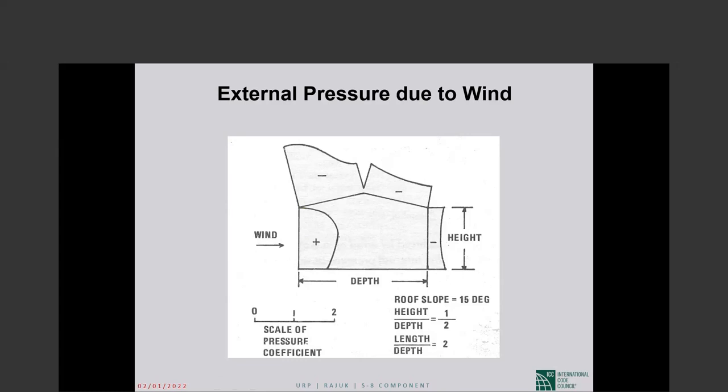And the basic point that I'm trying to make is that the roof has to be held down to the building, and very importantly, the building has to be held down to the foundation. That I have found missing. After hurricanes, I have with my own eyes seen whole buildings uprooted, sucked up from where they were, and deposited a couple hundred yards away.